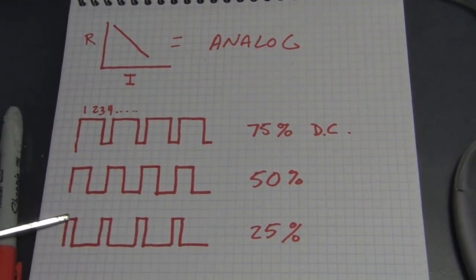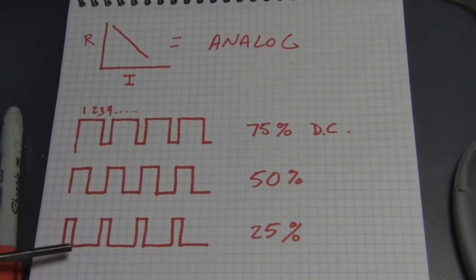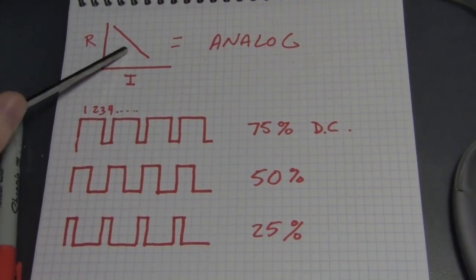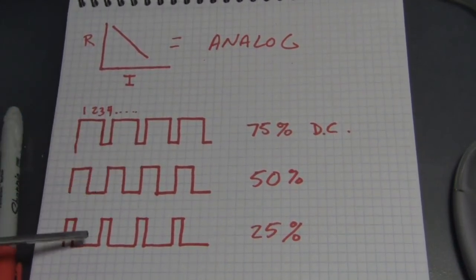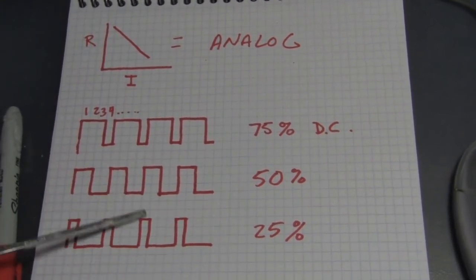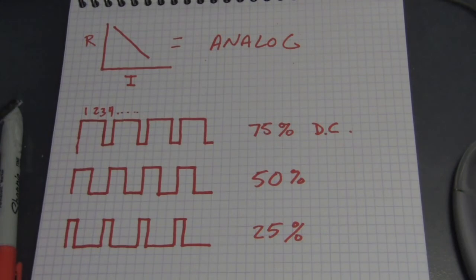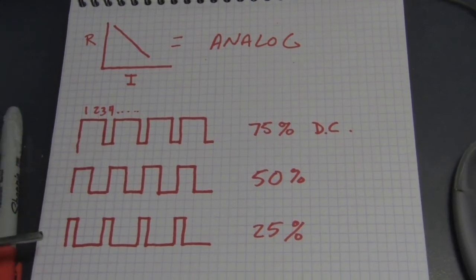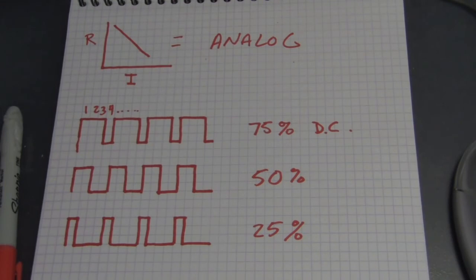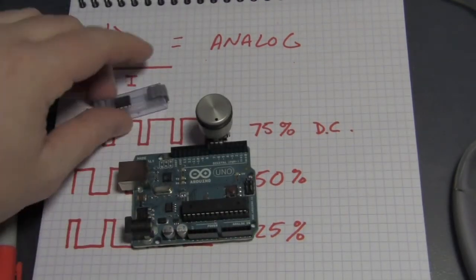Now each of these pulses runs at full current, so if you have an LED that changes tint as the current is reduced via more resistance, this might be a good way to go. It's questionable at this low level whether it would really save you anything with efficiency or be more efficient. I definitely think at the higher levels it could be more efficient because you don't need to have 100% duty cycle. I guess that's about it for this episode. I wanted to show you guys how digital PWM works, two means to do it, on a big Arduino and a little microchip.